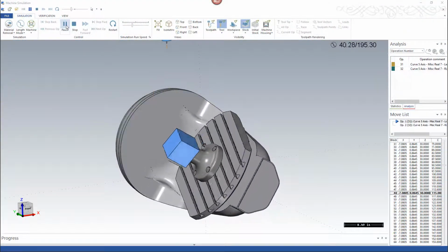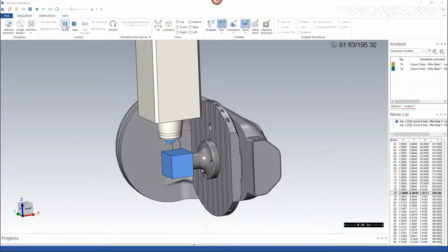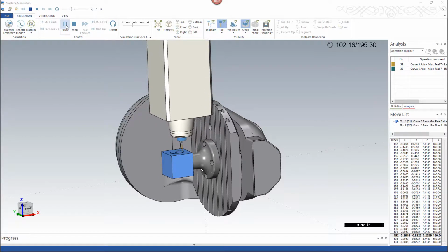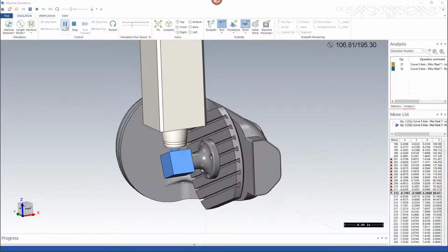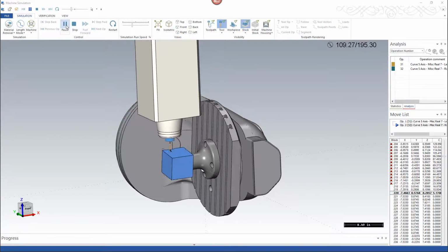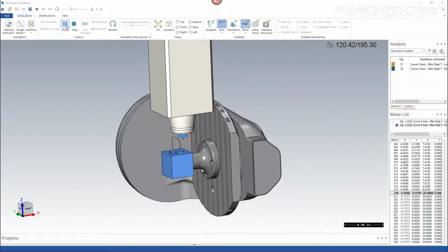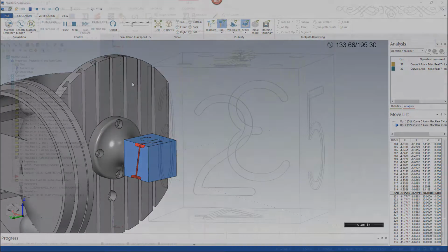Running these settings through the machine simulation, it becomes apparent that not using a retract between these two operations will be an issue. Using just the clearance heights between indexes will result in a crash. This may not be the case for all operations using the same tool, and you will need to keep this in mind as, by default, the post will apply logic to determine when retracts are needed, but you can override where necessary with this miscellaneous value.